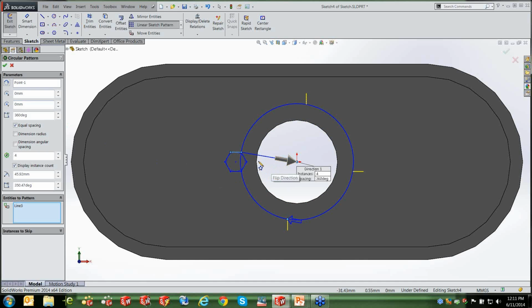Now, it also is going to take the closest point from the entity that you've selected, all right, the closest point, and it's going to draw this diametric circle, which we describe with a radius value, from that closest point. And as I start to select more points, you'll see the preview update, but also the circle updates, which gives you the diameter of the pattern.